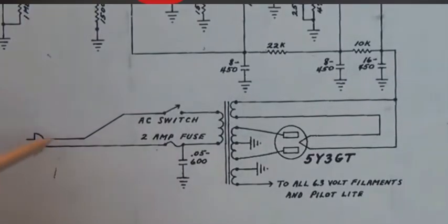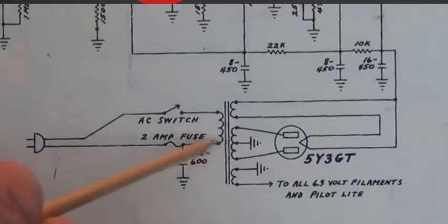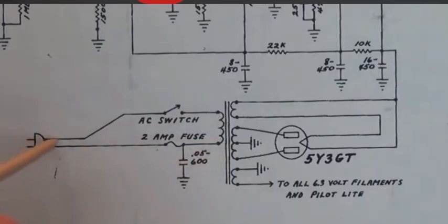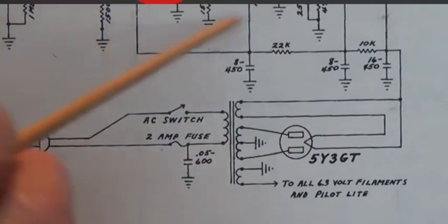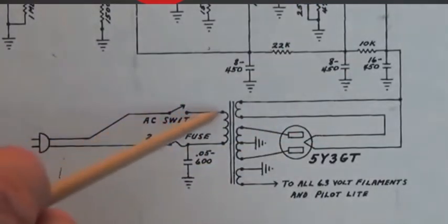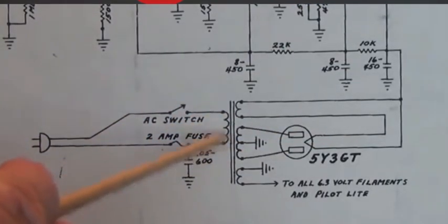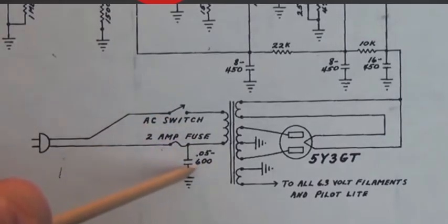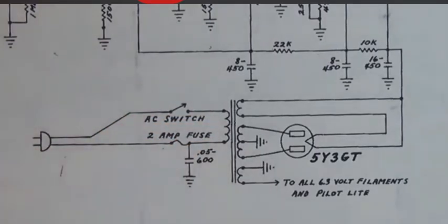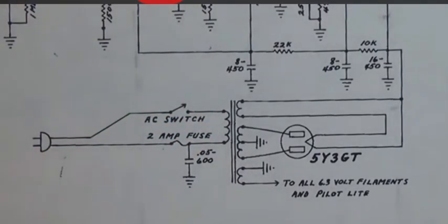The first of those chunks will be the primary windings of the power transformer, which is where the 120 volt 60 cycle power cord is connected. That's it. This is the only 120 volt 60 cycle current in the entire amp. I'm sure many people thought it's lurking up here somewhere, but it's not. It's strictly connected to the primary winding of the transformer. We have the AC switch, we have the fuse, and of course the all-important death capacitor. Okay, all of that constitutes the entire 60 cycle 120 volt part of the amplifier.